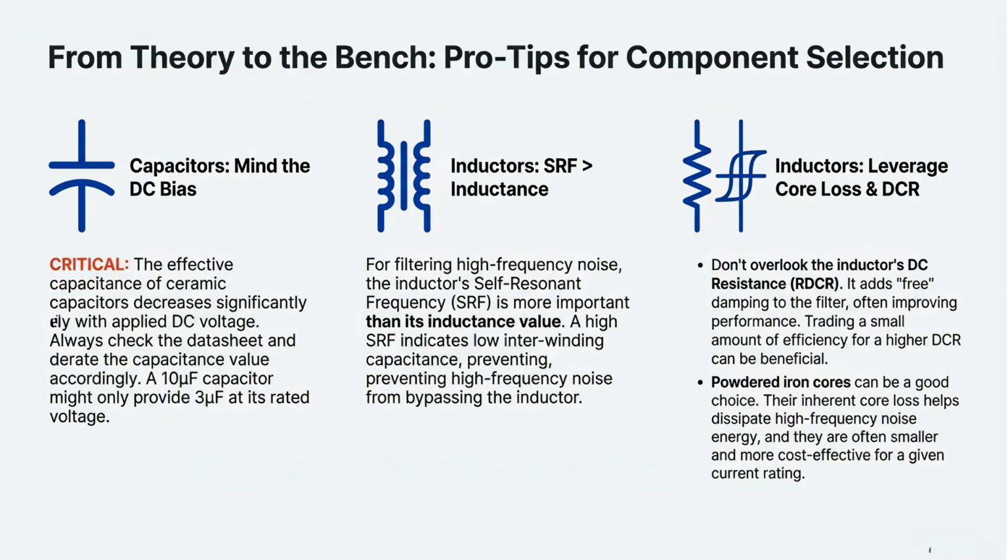For inductors, a high self-resonant frequency is more important than inductance for high-frequency filtering. Also, leverage core loss and DC resistance for free damping.